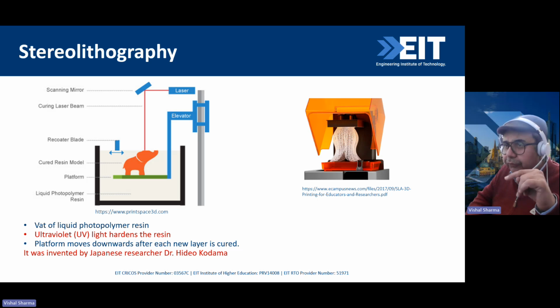The advantage of using stereolithography is we can get very fine detailing. Surface finish is very good, and aesthetics is very nice, but the parts are fragile. So these are not fully functional parts. These are only for aesthetics and looks, and we can try a few things on them. Surface finish is very good, but we can't create gears out of it. The gear's shape and size we can definitely see, but we can't use the gear in practice because the material is fragile.